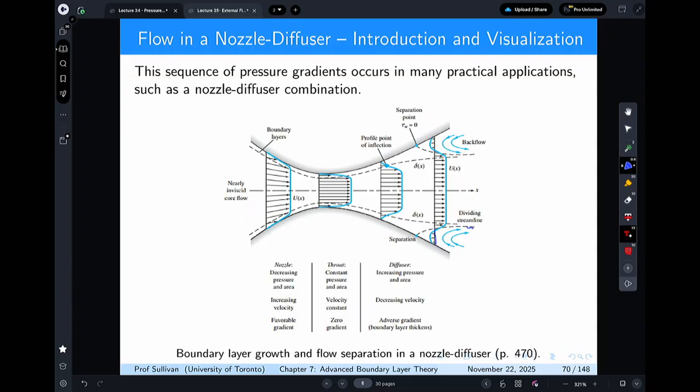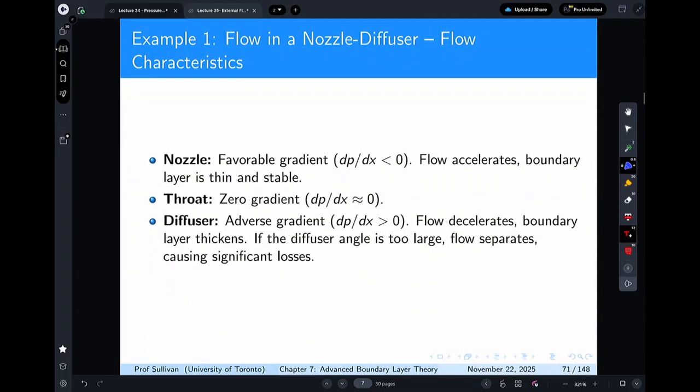However, when I look at it in a flow, I'm going to say, hey, that looks like a recirculation zone, and that's where I'm seeing this sort of circulation in the flow. So that's 2 ways to approach it, but generally, wall shear stress of 0 is the important criteria.